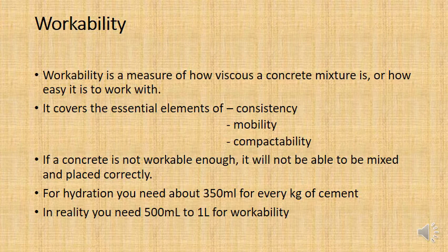Well, that's all related to workability. Those terms I used, ease of mixing, ease of placement, ease of compacting, ease of transporting through a pipeline, those are all given over to the term workability. What do we mean by saying that a concrete is workable? Well, it means it's easy to work with. So workability is really a measure of how viscous a concrete mixture is.